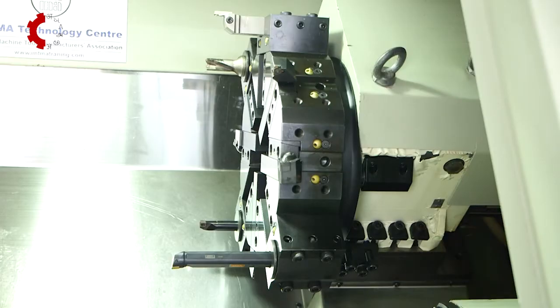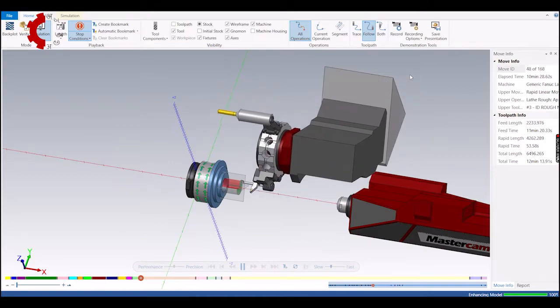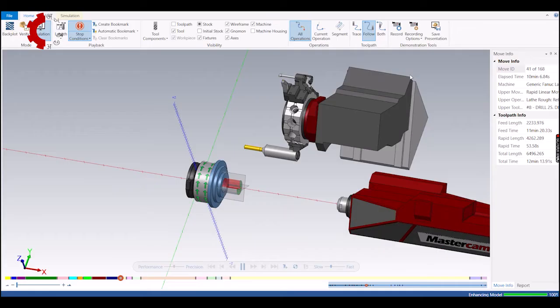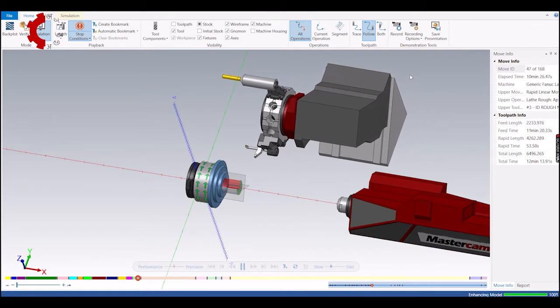We need many tools to machine a workpiece. These tools are clamped onto the turret tool disc. The cutting edge of each tool comes at a different distance in X as well as Z direction with reference to the turret tool disc. When each tool is moved to the UCS origin, the turret tool disc is at a different position with reference to the MCS.